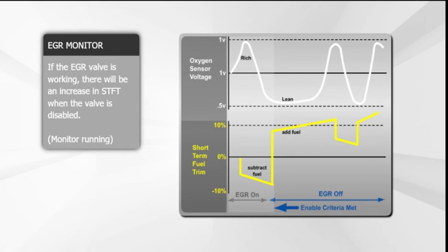The EGR monitor looks for changes in manifold pressure to determine EGR flow rate. Under normal conditions, manifold pressure should increase significantly when the monitor is executed or EGR commanded. This is due to the high-pressure exhaust gas flowing into the manifold. The MAP sensor provides the rational testing information to the PCM as validation of EGR occurring and that a change in intake pressure reflected EGR flow.